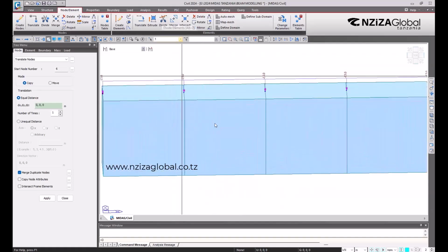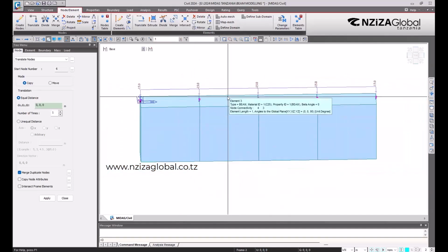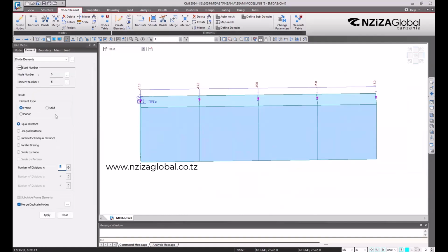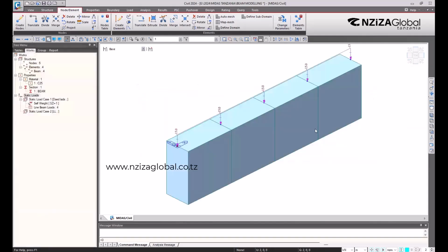You can even divide this into 4 subdivisions. When you go to divide, number of divisions. If you want equal, you say it. If you want unequal, you say it. For equal, you see they ask the number. If it's unequal, you have to define. Like when you are analyzing a beam, structure analysis, maybe the loads are at a certain distance which can't be in the middle. You can set the unequal distance, then you precise that load.